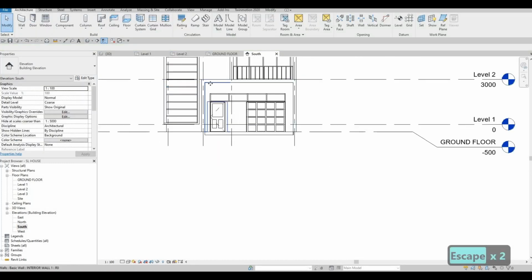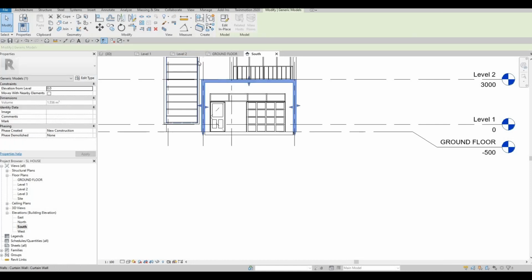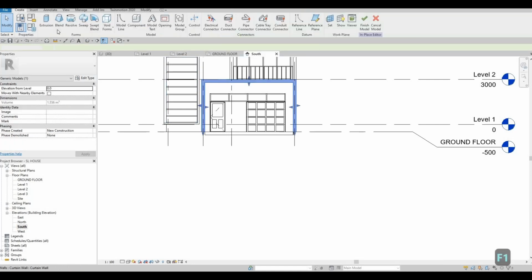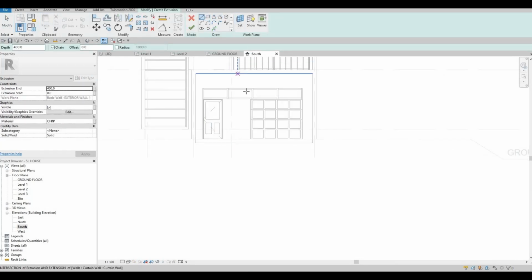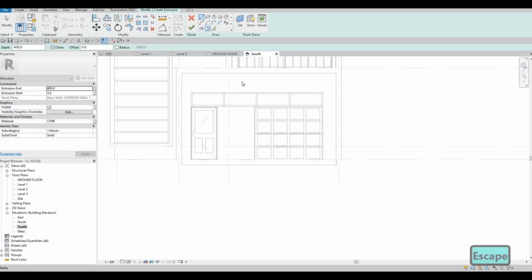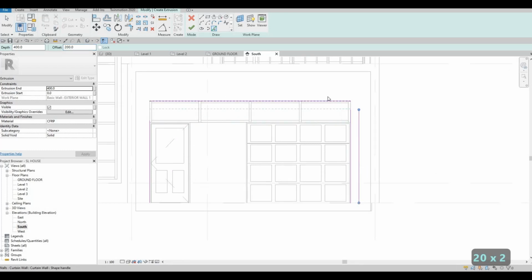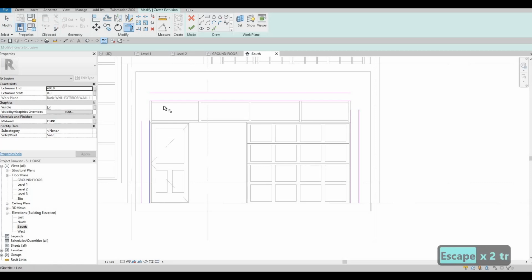and then at the same time select this one, add the same thing, edit, click here, pick path, or sorry, pick line, and then offset that to 200, and then use trim and extend to extend everything, or to fillet them, and then just use this.